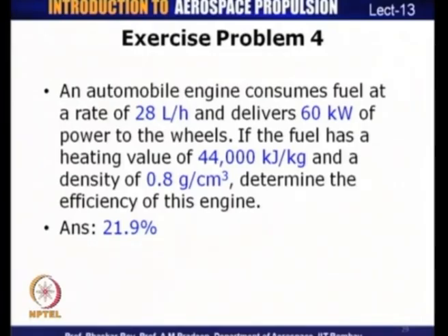So, here we have the rate of heat input in terms of heating value, and work output is also specified, and density is specified. The rate of consumption of the fuel is also given. So, based on this, we are required to find the efficiency of the engine, and the answer to this question is 21.9%. So, in today's lecture, we solved certain problems associated with heat engines, which is based on the principle of the second law of thermodynamics, as well as some problems on refrigerators and heat pumps.